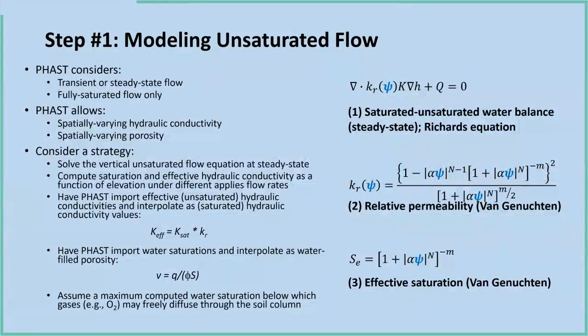Similarly, the product of the water saturation and the porosity, otherwise known as the moisture content, can also be saved as an array. This is clearly the water-filled porosity, and it will impact the rate of pore water movement and therefore the residence time in the unsaturated zone.